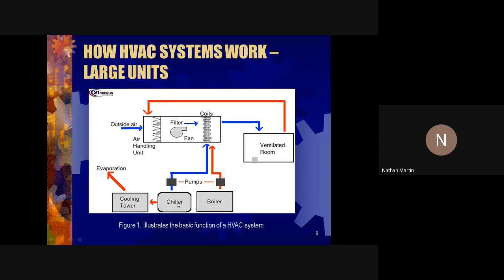Now, in your car, because most persons are familiar with the car system, what will happen is that you will pipe the hot water coming from the engine or from the radiator through the body of the car, and then return to the engine and then the radiator. The heat that passes through the body of the car is actually going to the coils inside under the dashboard.